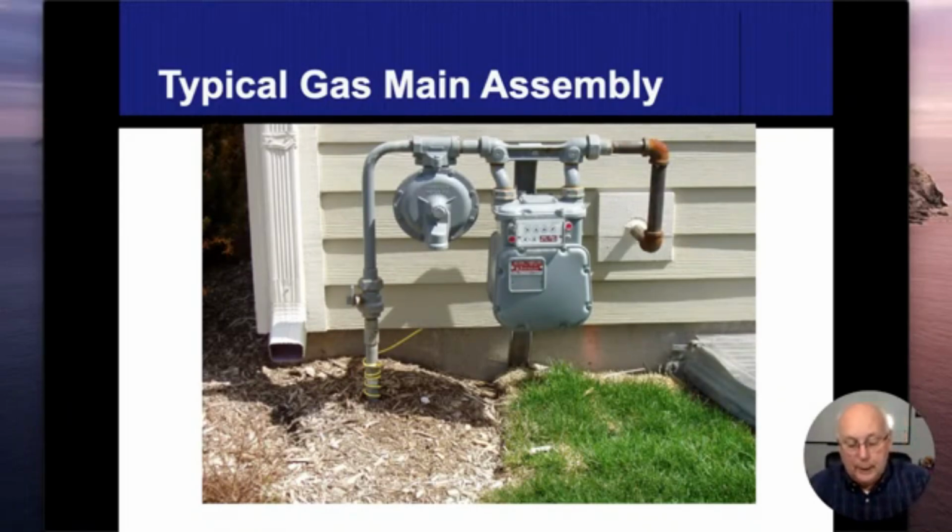All right. The last thing is going to be this tracing wire, this yellow wire that wraps around the pipe here. I'm sure we've all heard of Julie or whatever it's called in your area. Here it's 311. So before you dig, you want to get the joint utilities out there and mark where everything is. Because the gas lines are underground and they're plastic, we can't use a metal detector to find where they're at.